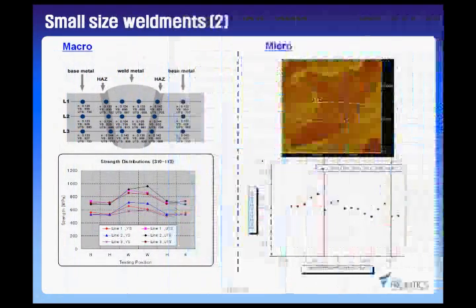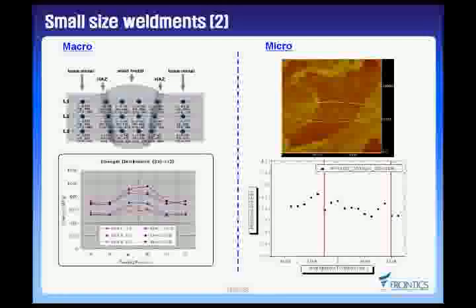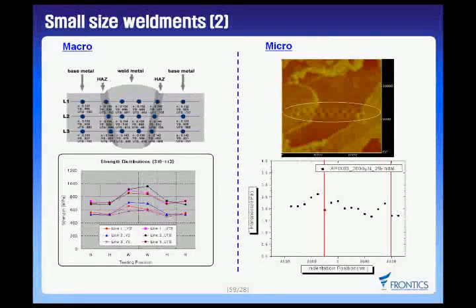The results show that the strength of welded metal is bigger than that of the heat-affected zone and base positions of metal. By performing along 3 lines, strength distribution was obtained. In the microregion, we also made a hardness map along the microstructure of API X80.